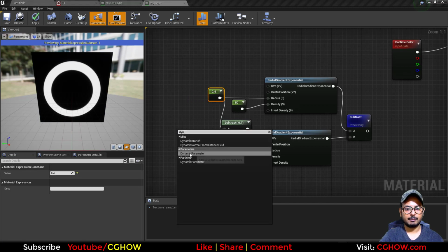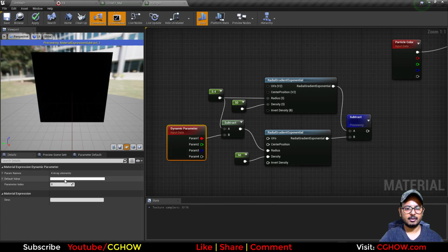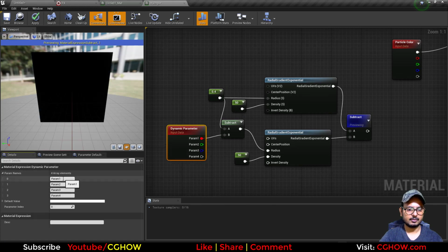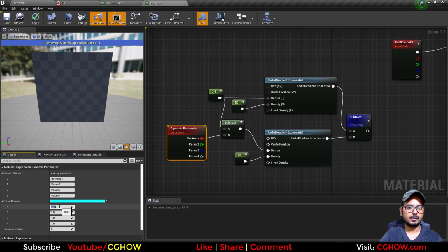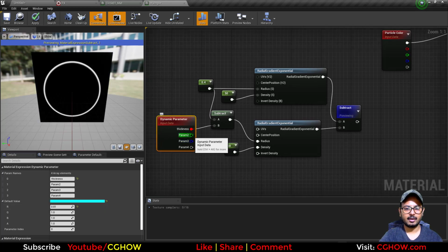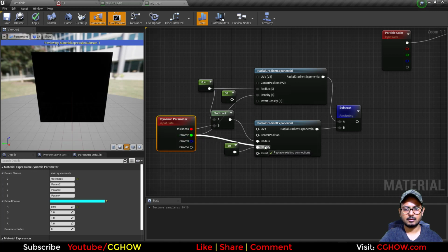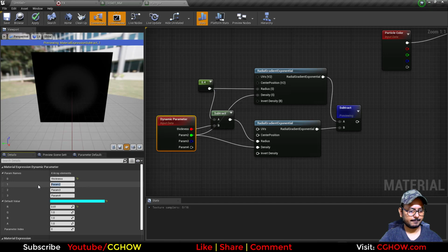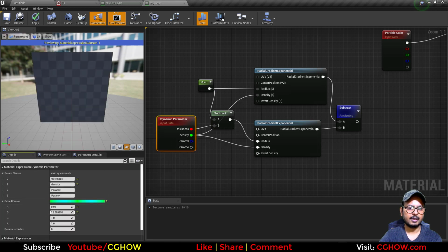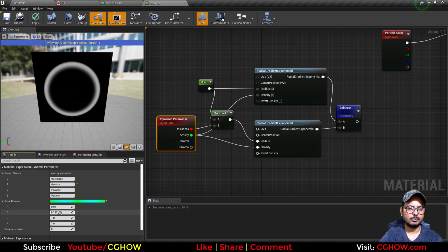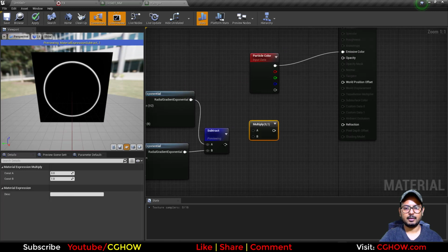And if I take the dynamic parameter now, it will decide the thickness. So thickness, and at 0.1, 0.2, 0.01, and this density, if I make a parameter of this, is my density, and currently it is 50, but I can decrease it so it will be slightly blurry, that I can use to make glow. So 50 by default, and multiply this with your alpha,